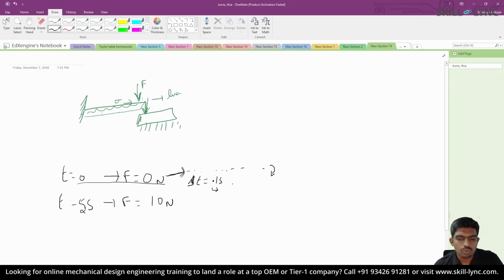Then the solver will move to 0.1 seconds and redefine all the matrices depending upon the previous step, and find the unknowns in this current step. After this particular step, it will again increment the solver time by 0.1 seconds, and this process will go on. In case your solver experiences a convergence issue, that is, if the solver is not able to get the same result while iterating to find the unknowns, it will increase the time step by some factor.